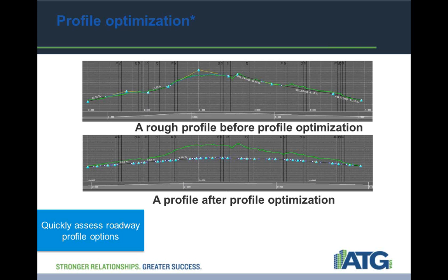With Infraworks 360 2015, there are new features, including new maximum fill height and maximum cut depth parameters that allow the user to calibrate the optimal placement of tunnels and bridges. New construction cost estimates for tunnels and bridges take into account tunnel and bridge style information. You also have the ability for variable side slopes and swath widths for earthwork computations.